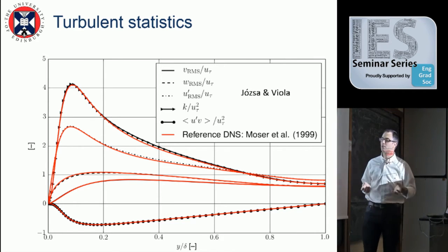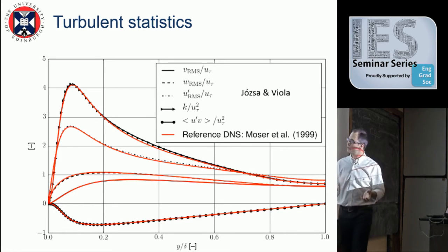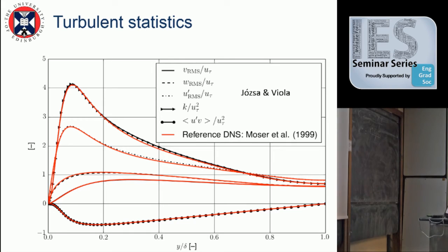But very importantly, if you want to be sure that your turbulent structures, these vortices, are correct, you cannot just take the mean value. What you have to do is look at statistics. Here again, this scale is not logarithmic, but it represents the same. Here you're at 0, at the wall, and here is the top of the mast of the sailing boat, if you like. You have to look at the first order statistics.